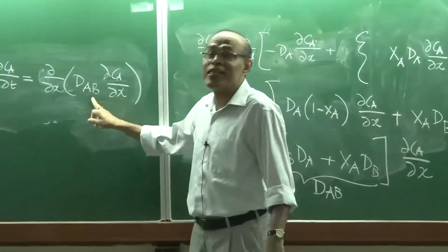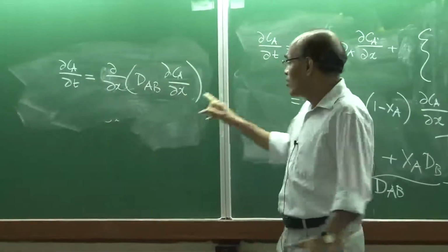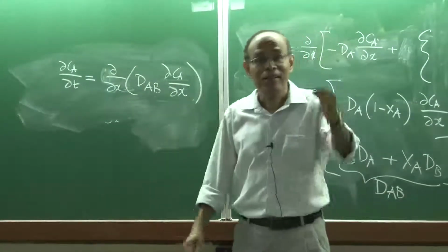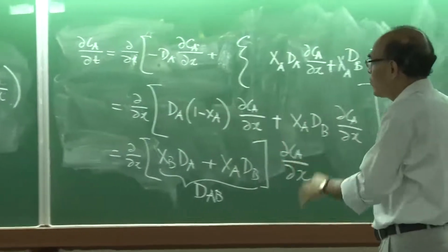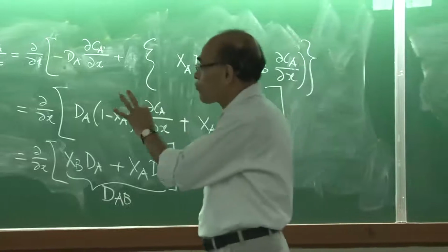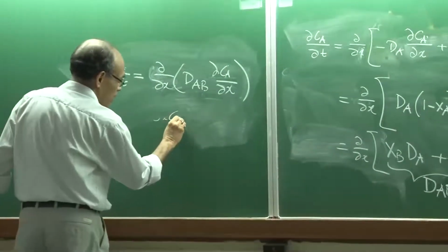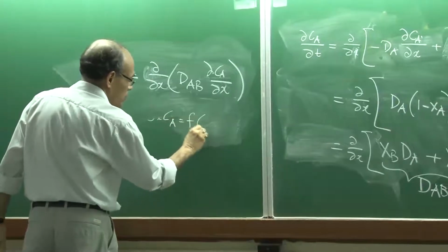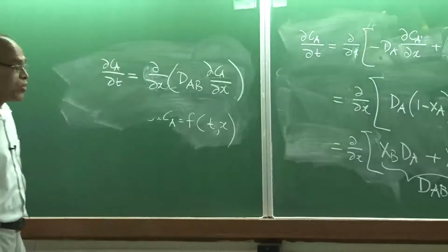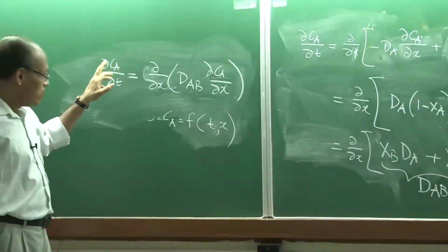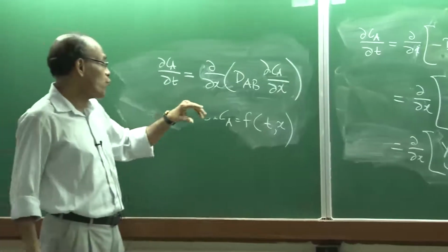We have to use an interdiffusion coefficient, and only then, if we solve this one-dimensional equation with respect to the boundary conditions, will the correct concentration profile of copper come out as a function of t and x. So we can then predict C_A as a function of t and x. So in such systems, A and B, where there is a large difference in the diffusion coefficient values.